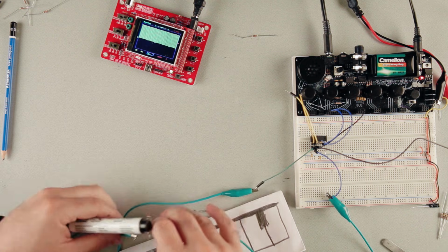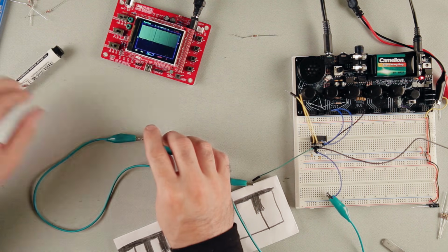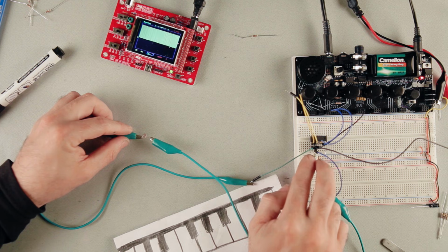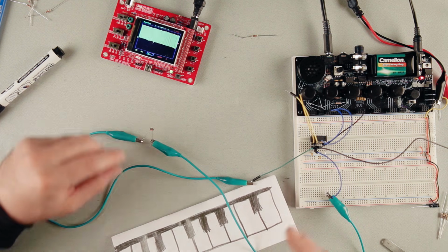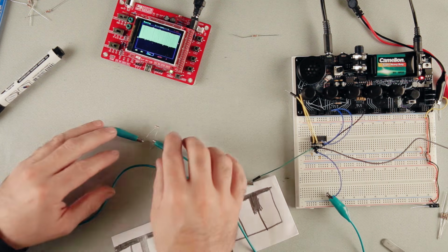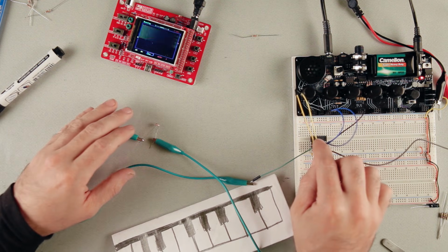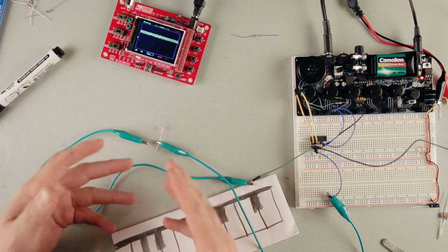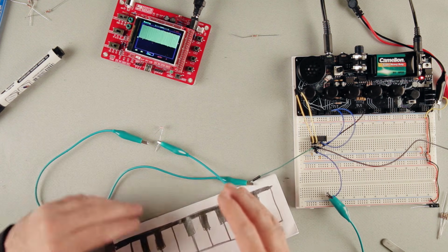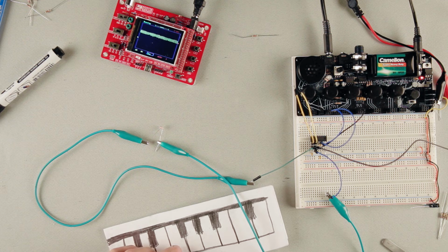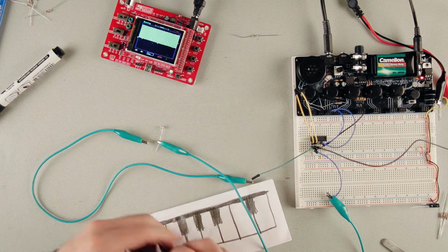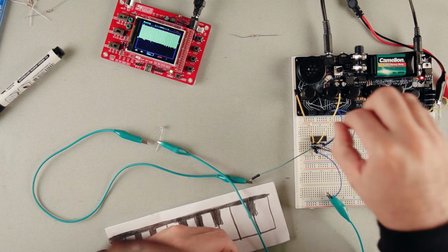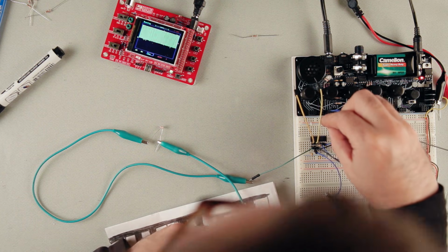Okay, so now we've covered a bunch of different ways of changing the pitch. And we've built a couple oscillators. Now, next what I want to do is we're going to build another oscillator, and we're going to start playing with creating relationships between oscillators. So we've already done that with the sync, where one of them is syncing the other, but now we're going to make an LFO, and that's going to modulate the pitch of one with a much lower oscillator. So I'm going to take a large capacitor, so I'm using a 10 microfarad, oops, and I'm going to make that oscillator right here at the top.